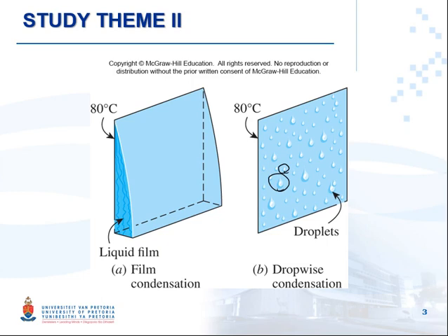So it is acceptable to say that dropwise condensation is the preferred mode of condensation due to lower heat transfer resistance and should be used in the design of heat transfer equipment. But many researchers tried for a long time to achieve sustained dropwise condensation, because it's not important to get it for a short period of time or once.